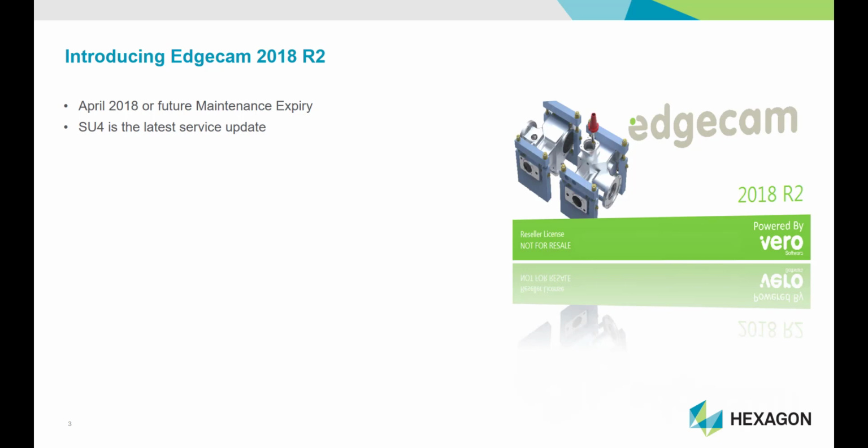I'd like to start off by mentioning that Edgecam 2018 R2 requires an update expiry of April 2018 or future. As part of installing the software, it is also a good idea to update your license so that you're able to use the latest software. Another quick note is that SU4 is the latest service update as of this presentation. This update is available for download from the Vero customer portal. As always, Edgecam service updates are historical, meaning they include all the previous updates, so you don't have to go and install SU1 and then 2 and so on.